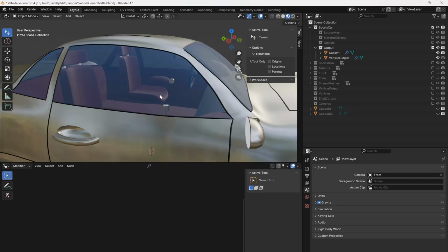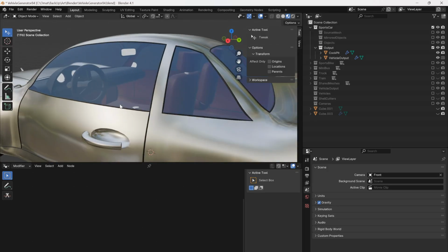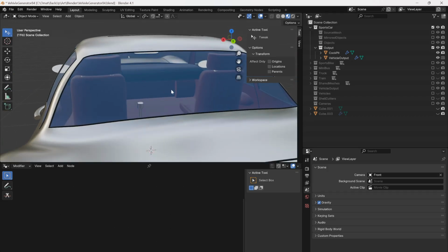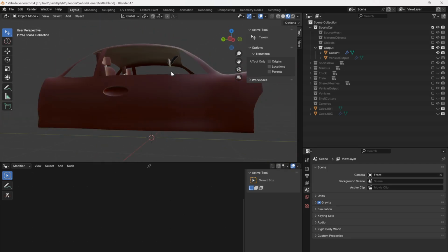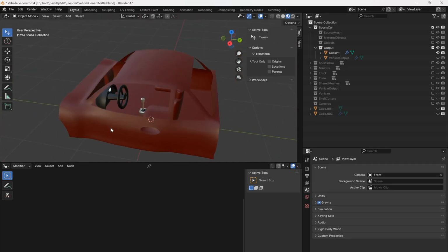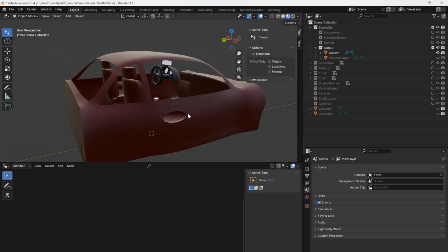And all this material here inside, it has it like, just show just the cockpit, so with a boolean operation, it will separate stuff from the hull mesh, and then take the windows out after the boolean operation.